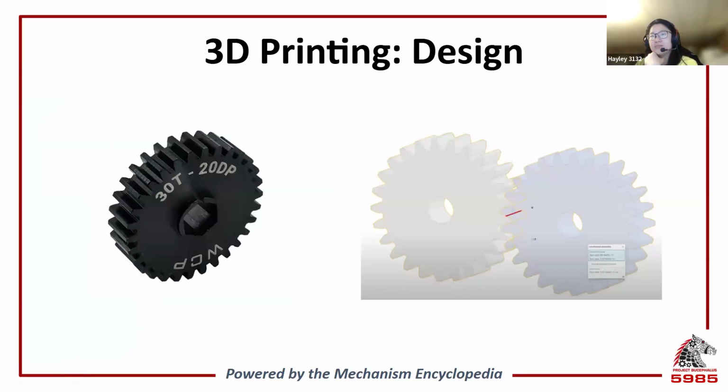So now we're going to go on to gears. When it comes to gears, you might remember that we talked primarily about spur gears. Whilst they're the most efficient type of gear, they're not the best. They're great for metal gears, but when making them out of plastic, we want to minimize the tooth pressure to avoid breaking the teeth off.